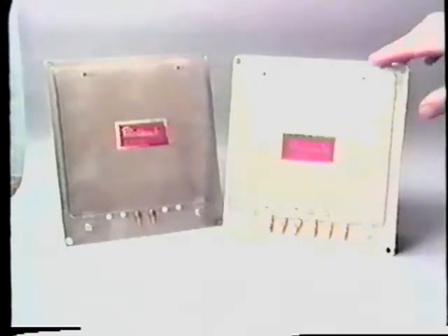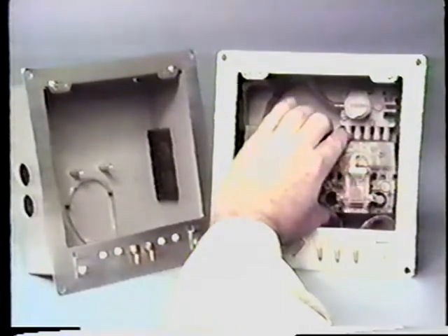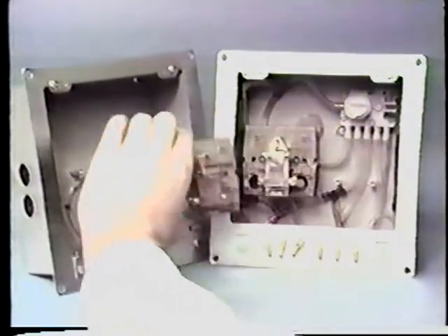The transmitters are factory calibrated and should need no adjustments at the time of installation. However, the alignment of the transmitters can be checked by comparing the output of each transmitter. The unit is shipped with both transmitters mounted in the return air mounting box to facilitate the alignment process. After alignment, the outside air transmitter is removed and mounted in the outside air duct. To align the transmitters, the unit should be mounted in the return air duct of an operating system for at least 2 hours in order to stabilize it.